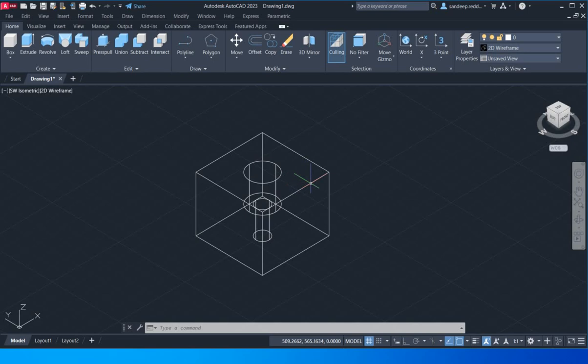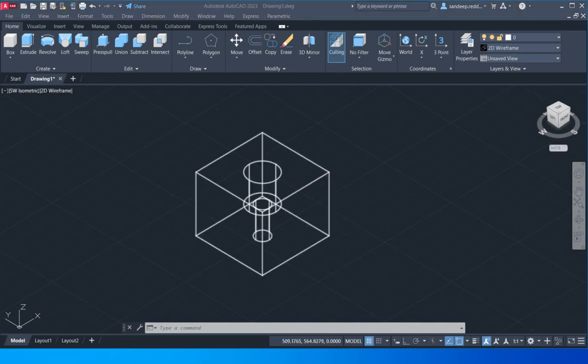So here it is handy to understand how sectioning works. What sectioning does is it does not actually slice the object, but it creates a section plane, so that you can understand that this is a section plane. So if you are asked to draw the sectional view, first obviously you will define a section plane, and from which you will generate the sectional view or the sectional orthographic view.